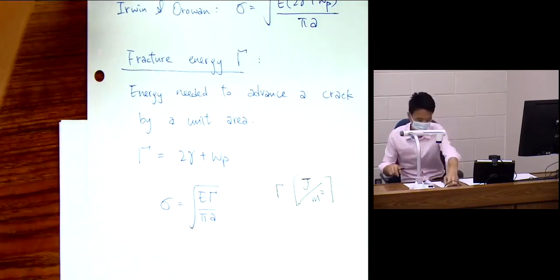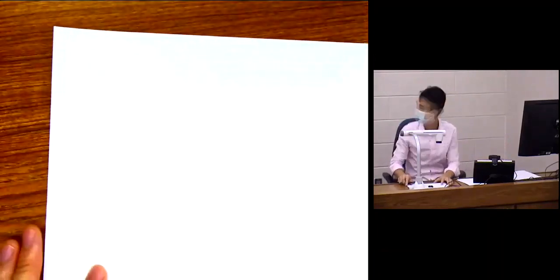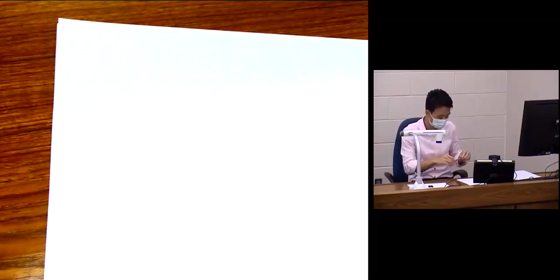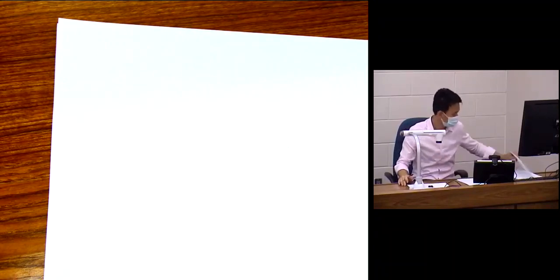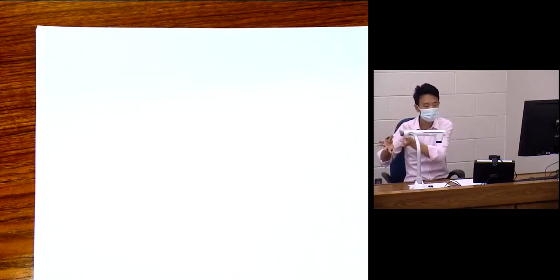Now, fracture energy is a material property. It is not dependent on the crack length, and we can measure that from experiment. So this is something we can get. And typically it's much larger than surface energy, right? Because you have more than just surface energy happening at the crack tip. Now, that's good. We have defined an energy based on the material resistance to fracture.